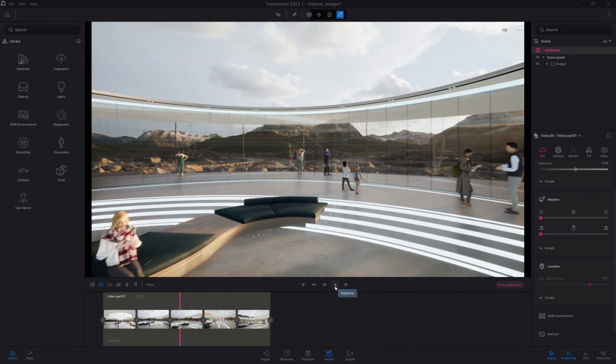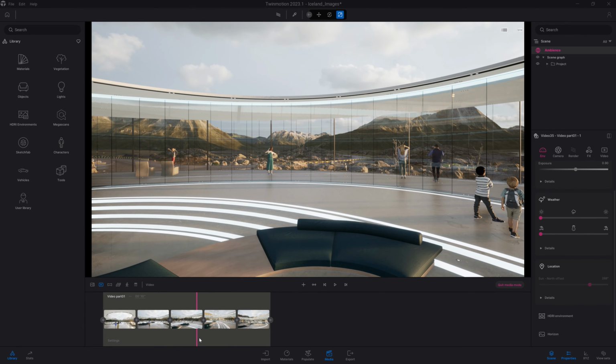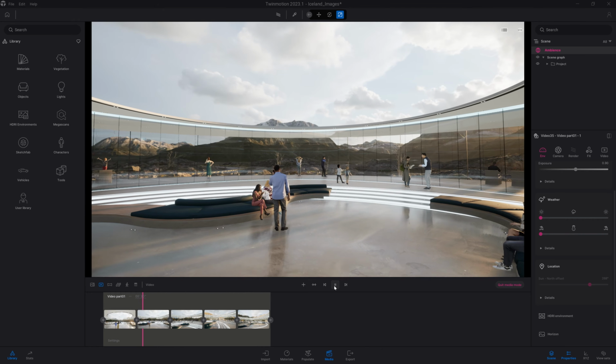So obviously I want something a bit smoother, so what I want to do here is come to the top of my part here, and I want to edit that time. Maybe something like 30 seconds will work a bit better since we've added quite a long movement. So now I can click back on the play and it will be much smoother.